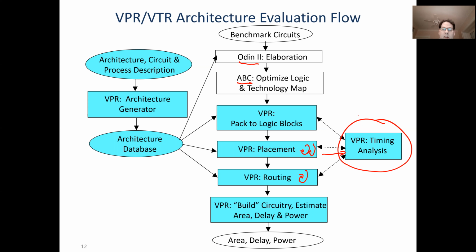Logic synthesis, I haven't actually drawn a line here for logic synthesis. So elaboration and technology mapping can be timing driven, but they actually benefit much less. They're early enough in the flow that their estimate of where the design critical path is not that accurate. So most logic synthesis tools don't make much or often any use of timing information. Instead, they try to minimize the logic depth, which is what I just showed you a few slides ago. They try to minimize how many lookup tables are connected in series. And they try to do that all over the place because they just don't know where the critical path will be.